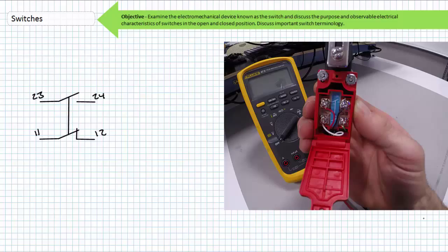When we crack open the limit switch, we're presented with two noticeable differences between this and the previously inspected emergency stop and push button packages. One, tiny Lilliputian wires. This limit switch is obviously rated for lower current and voltage than our previous devices. This is awesome and totally makes sense. A limit switch is a sensory device only. Why should it carry high current or use high voltage? For that matter, why would a push button?